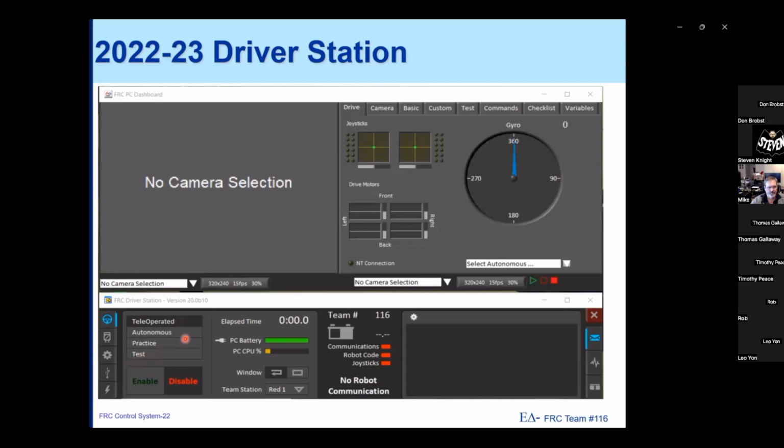And any of these individual options here, when you select them, if you're looking at the teleop, autonomous, etc., you'll then click the enable button, and then that will turn the robot on. Now, according to the normal FRC rules, we want to make sure that we announce to everyone when we get ready to press the enable. We'll typically say enabling, and then everybody knows to get their hands out of the robot so that nothing happens, especially if you happen to have the autonomous setup here.